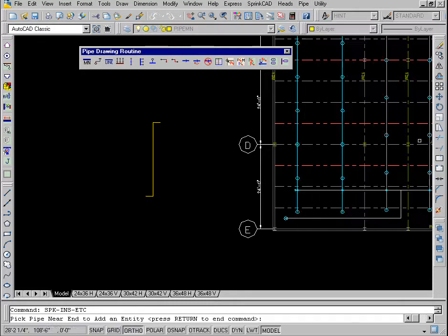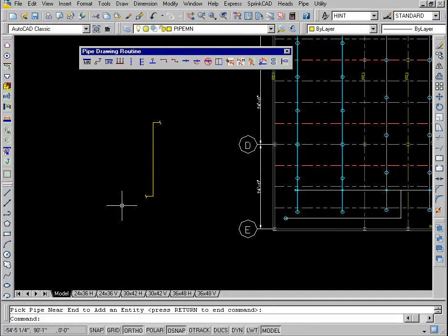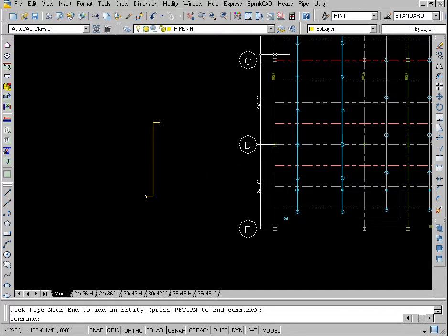Select Etc. symbol from the Pipe, Miscellaneous Pipe pull-down menu and insert the symbol at the ends of the pipes as shown. You now have to connect the section view to the rest of the system so that it will be considered for hydraulic and stock list calculations.